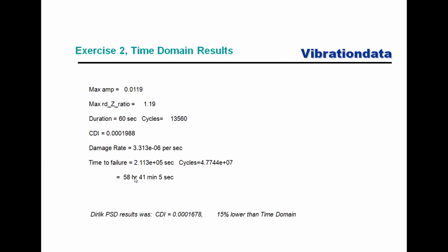So if you wanted to be conservative, you get a couple choices. Just for the synthesis process, for example, you could try synthesizing 2 or 3 or 4 different time histories, because those are not unique anyways, and running this calculation maybe 3 or 4 different times to see what the minimum time to failure was amongst those 3 or 4 cases. But at the end of the day, let's just realize that these are all ballpark calculations anyways. That's just something we have to face.